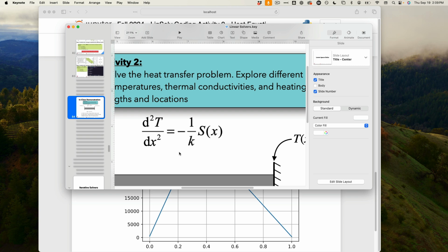Right? So we expect as K approaches infinity, or very large values, the source term contribution is insignificant, because whatever heat is going to transfer to the rod, it's going to be dissipated very quickly through the rod. It's going to go through the ends, 500 and 300, whatever direction it wants to go. Mathematically, this means that distribution is just going to be linear.